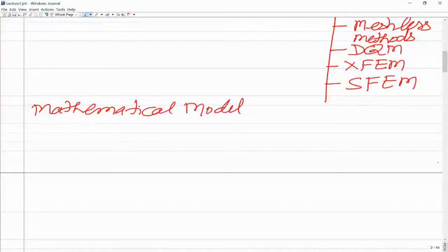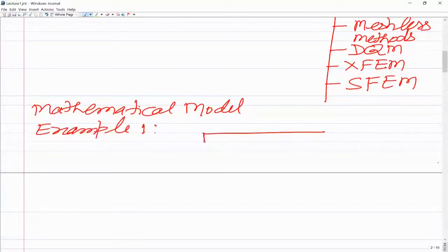So the first example I'm going to take, example 1, is a rod under axial load. Typically we call that a truss, not the truss structure, but the truss structural element. Some kind of stiffener, although stiffeners may also undergo bending, sometimes you can idealize that. Or let's say a missile is subjected to thrust forces, drag force, and those kinds of things. Predominantly the deformation is axial deformation. That kind of structural element can be modeled using this.